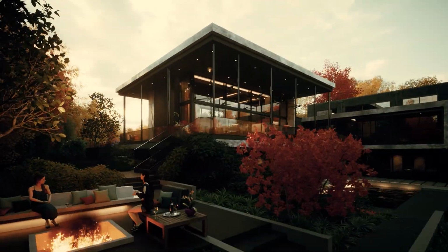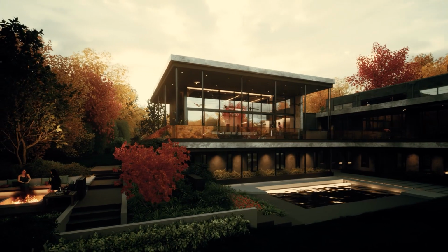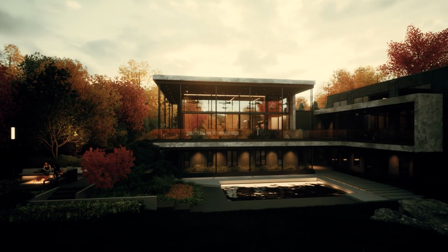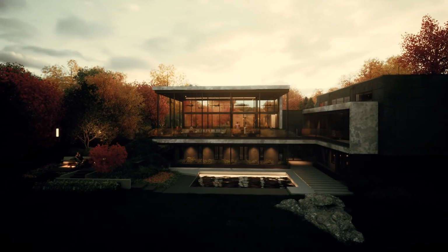Okay, so the next step in the design development process is doing a structural engineering evaluation. Now, on this particular house, the yard house, we needed to have a structural engineer. We knew that going into the design development phase because we've got a lot of glass. And like I've spoken before, if you've got a lot of glass, you're probably going to have steel because you don't have a whole lot of resistance against lateral forces. So let's go over real quickly kind of an initial meeting, what the first meeting with a structural engineer would look like on this particular house.